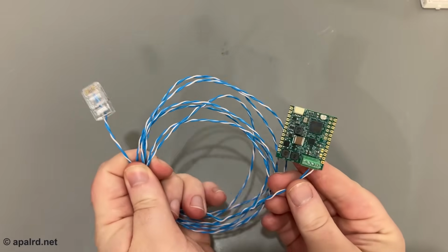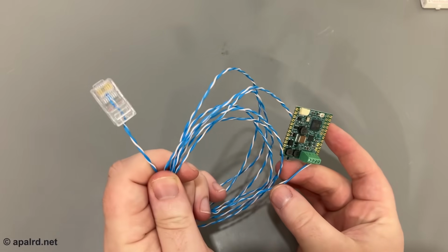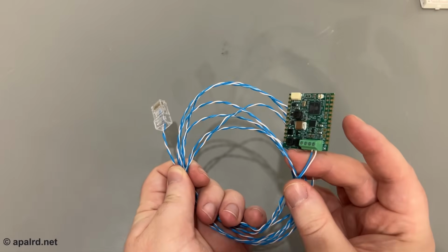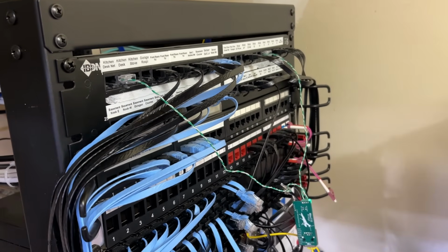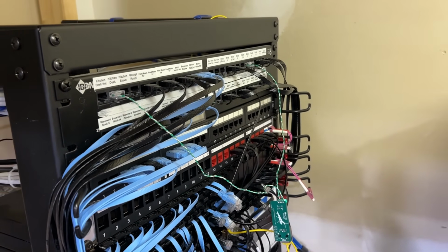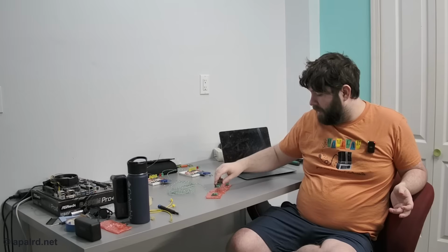I actually crimped on some RJ45 just using the center pair and ran this across my home, and I put these in separate rooms. I put the Mantis bridge in the middle down on my rack here with my PoE switch. Worked great. So that's with the terminating resistors in the center of the bus, which is probably not correct, but it's probably half decent. And about 10 meters in each direction, and it worked fine for me.